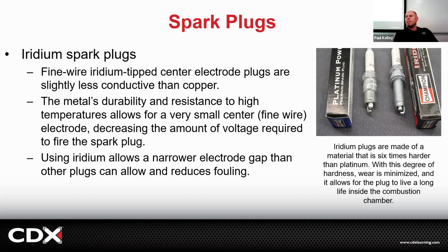But let's say it's a platinum or an iridium coated plug. Should we gap them? You could verify the gap, but you don't have any business shoving something in there that's going to scrape it. You could basically look at it, and if it looks like it's good, it's good. Do you know what happens if you take an iridium spark plug and, let's say, the parts employee is walking and drops the box? Do you know what you're supposed to do? Junk that box and get a whole new box. I mean, it's pretty crazy, because if the tip gets bent and you have to straighten it, it's no longer properly coated, you're done. Right?